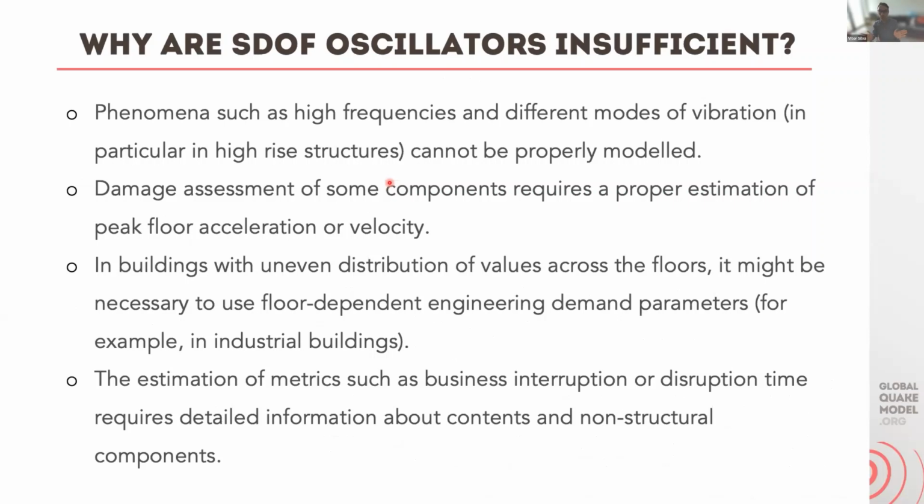Why do we also need to move to other methodologies? Why might single degree of freedom systems be insufficient, and why are we going through this phase of trying to expand the vulnerability methodologies? So there are many phenomena that cannot be captured by single degree of freedom systems. I'm only including some here, but for example, higher modes of vibration are not well captured. Obviously also torsional effects and so on.